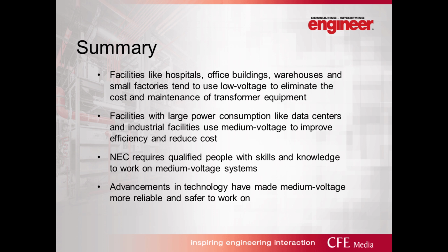The larger facilities that consume a lot more power, like the big data centers that are 100 megawatts and so forth, and large industrial facilities, use medium voltage just to improve the efficiency and reduce all that cost of copper. From NEC, the NEC does still require qualified people with skills to work on that equipment. If you work on medium voltage equipment, they have to be trained for that, and that can be an issue.